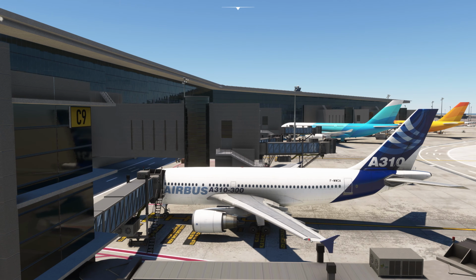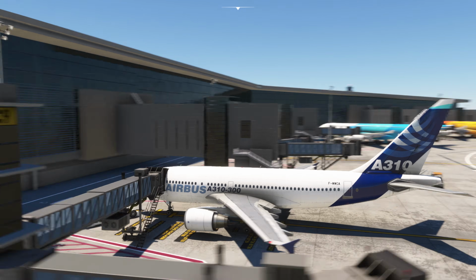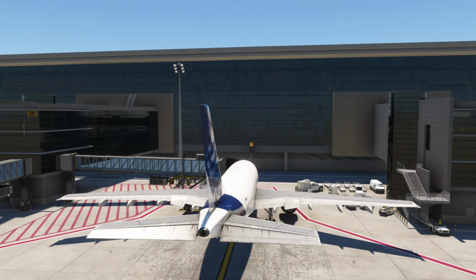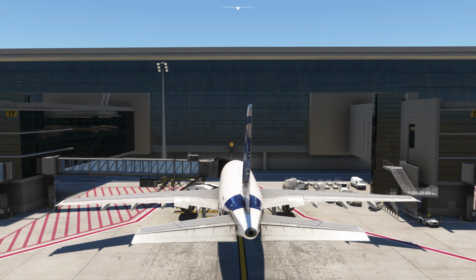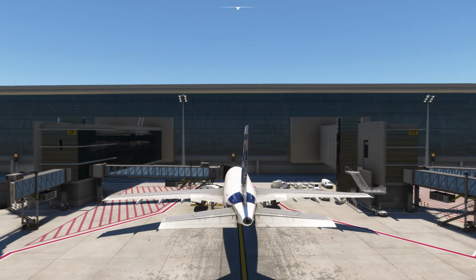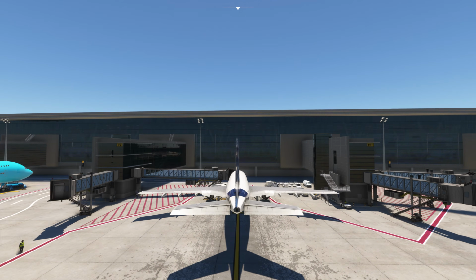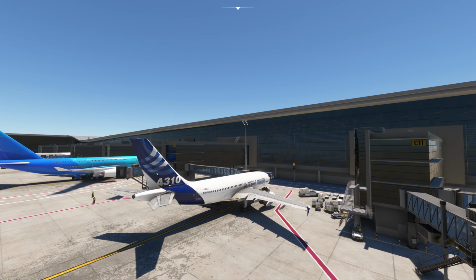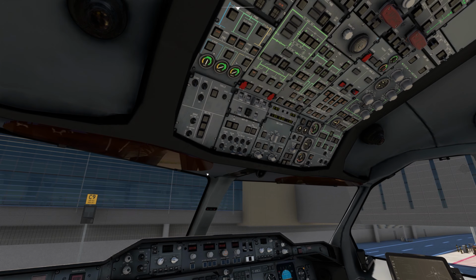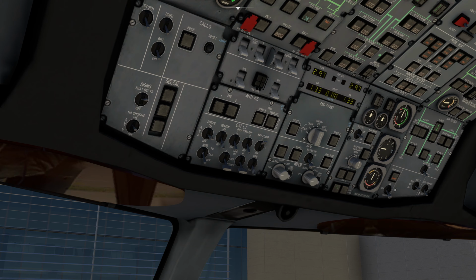Similarly, on the left hand side, there is a red light which tells other planes that the plane is moving towards the left side. And then you have these two bright lights at the tail of the plane. If any other plane is looking at this light, it knows that it's looking at the plane from the back side. And then you have lights over here on the tail, which is your tail light. So now I've turned on the logo light, and I have turned on the nav light.